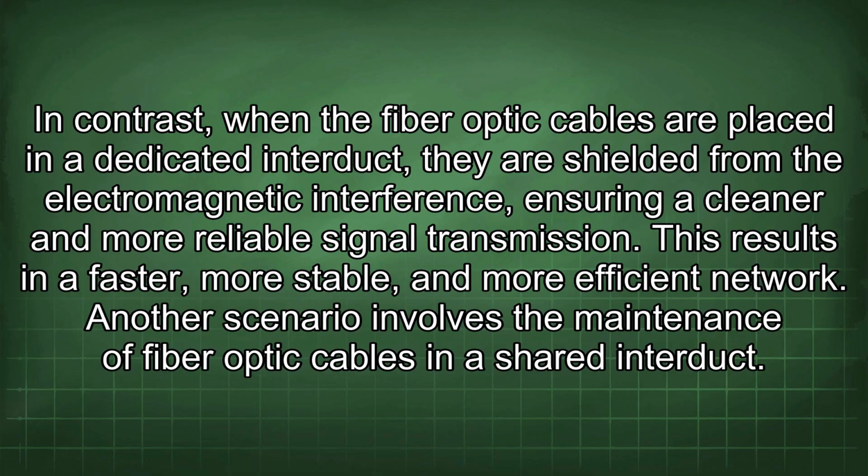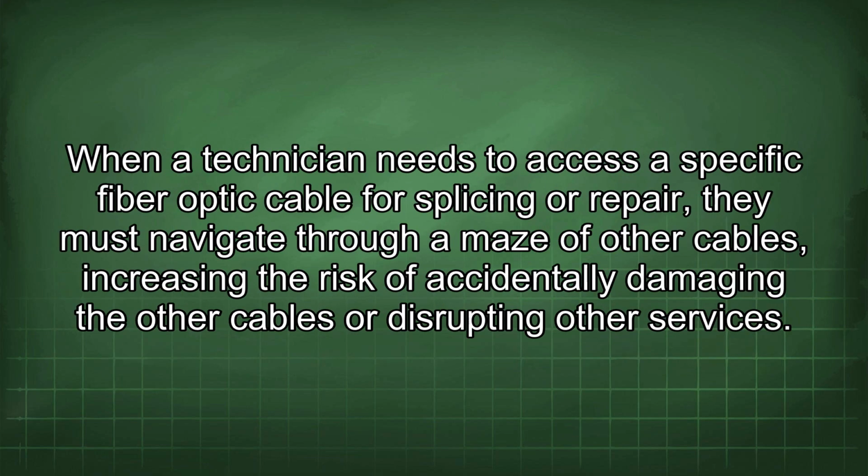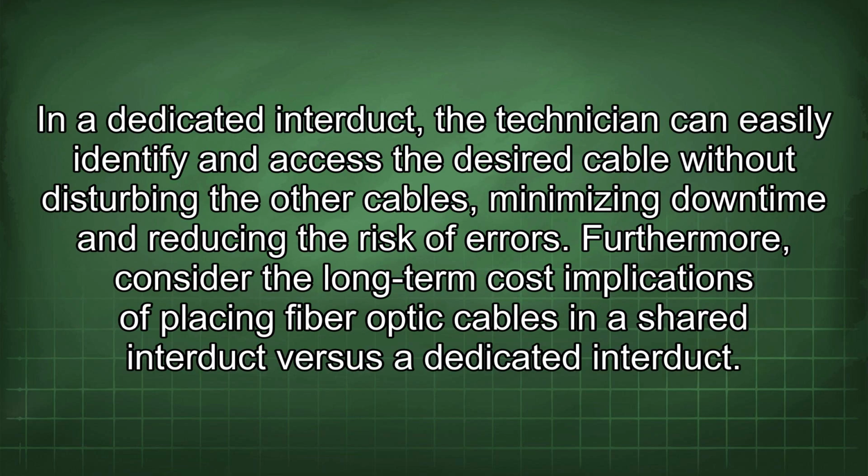Another scenario involves the maintenance of fiber optic cables in a shared interduct. When a technician needs to access a specific fiber optic cable for splicing or repair, they must navigate through a maze of other cables, increasing the risk of accidentally damaging the other cables or disrupting other services. In a dedicated interduct, the technician can easily identify and access the desired cable without disturbing the other cables, minimizing downtime and reducing the risk of errors.